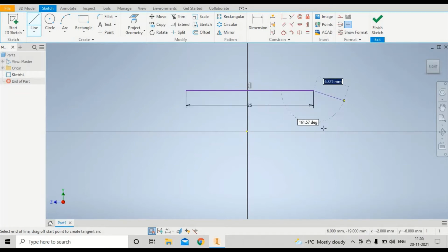Now this line is still continuing. You need not take the feature once again. Now I'm positioning at this angle. Now I want to draw this at an angle of 135 degrees. So what I can do, I need to press the tab button and 135. Again tab button. Now I need to provide the length.